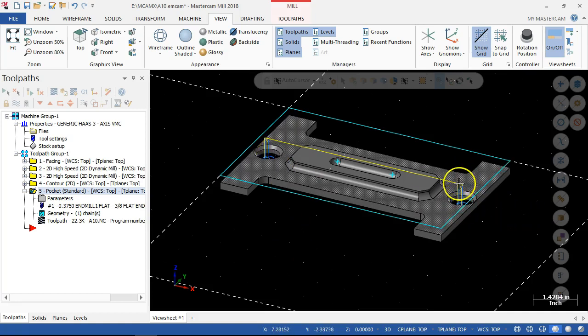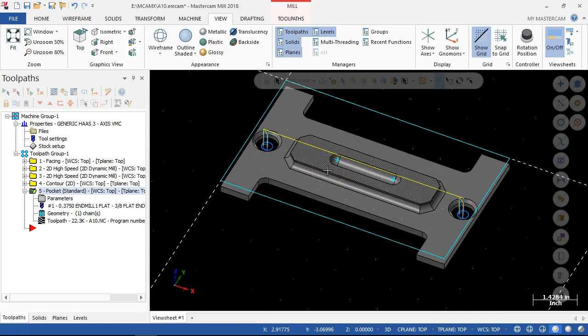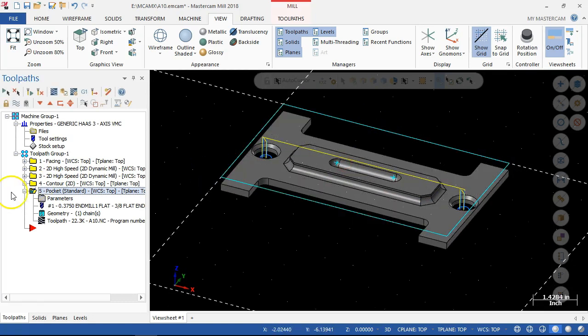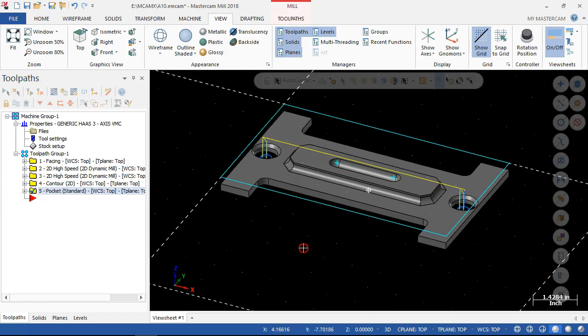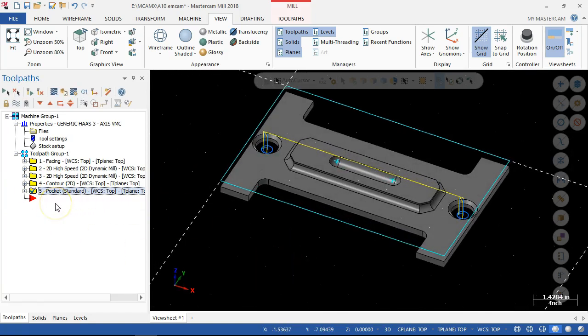It's still going to retract, move over, but I'm okay with that and can probably even find the keep tool down, but keeping the tool down makes me nervous here because in that other condition, if we'd missed that, keeping the tool down might plow through the center of the part. So pay attention to what you're getting for those rapids and those linear tool movements. All right, let's see. We have the 2 ball end mill.